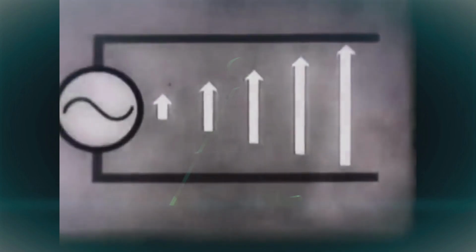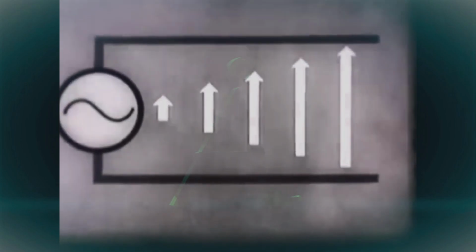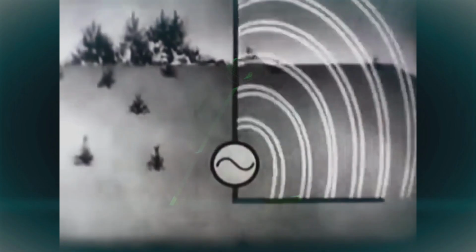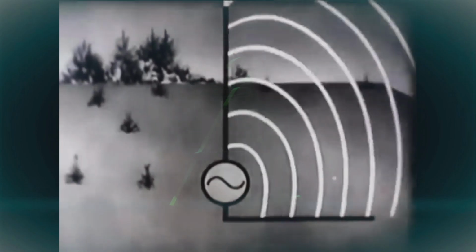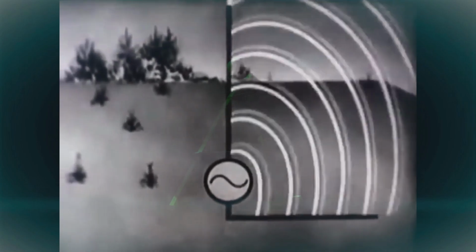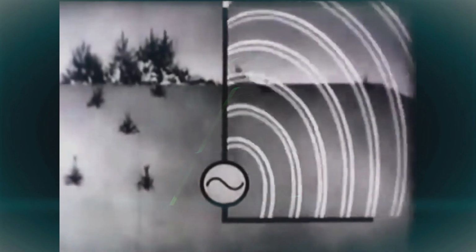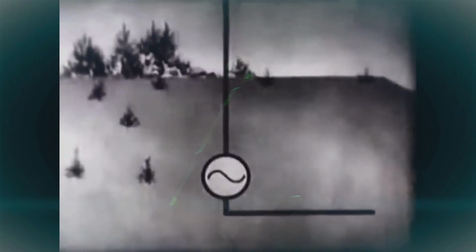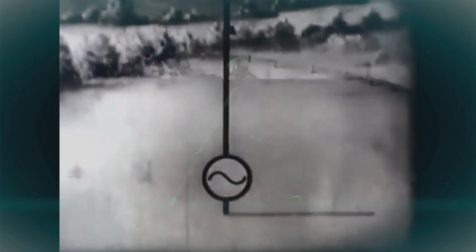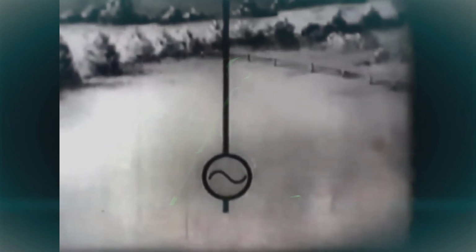What can we do about this? Well, the same quarter-wave transmission line holds a few more tricks up its insulation. When only one wire is moved perpendicular to the other, the closed electric field which existed between the upper and lower conductor becomes a partially open field. Since the lower conductor is grounded, similar electric fields occur all around the upright conductor. Our upright conductor now functions as an antenna, a quarter-wave antenna. The quarter-wave transmission line with one conductor upright is quickly changed into a practical antenna system.